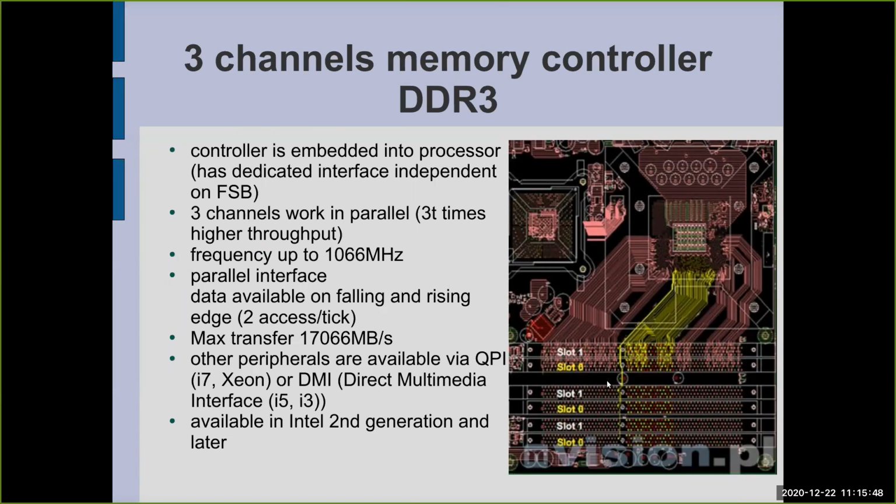Look, here you have a scheme for DDR3, so it's quite obsolete, but okay, it's valid also for DDR4 and even higher. Here you can see the bus. The memory controller is the only interface in current computers which is parallel. So here we have many lines, more than about 100 lines.